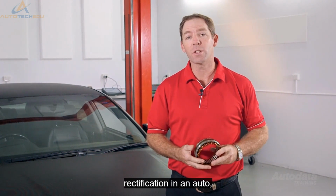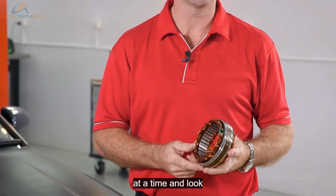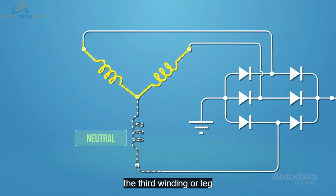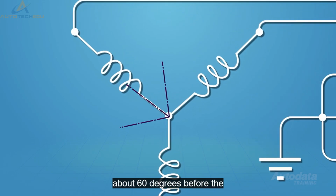To understand full wave rectification in an alternator, we need to take into account current flow through Y and delta windings. Let's take this one step at a time and look at the current flow through each leg of the Y stator as influenced by the rotor's north pole. Each circuit in a Y or star type stator is made up of 2 legs connected in series. When a pair of windings is used to generate current flow, the third winding or leg is said to be neutral. Since each winding is separated by 120 degrees of rotation, current flow through each begins about 60 degrees before the leg to 60 degrees after.